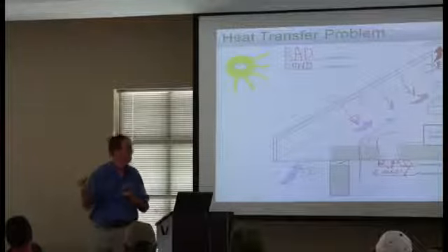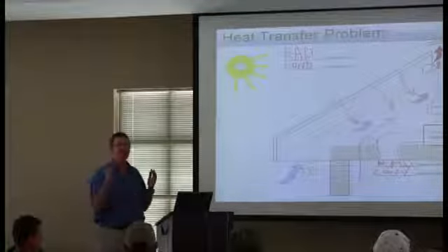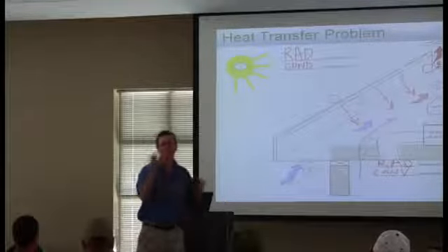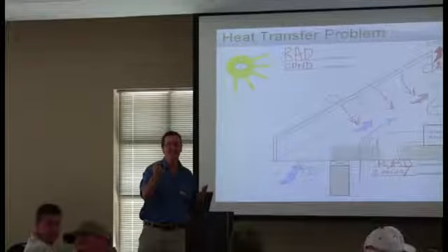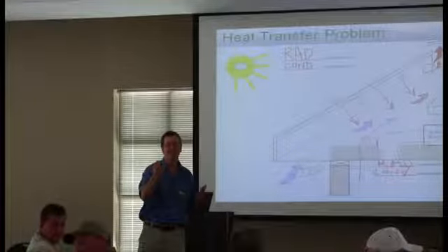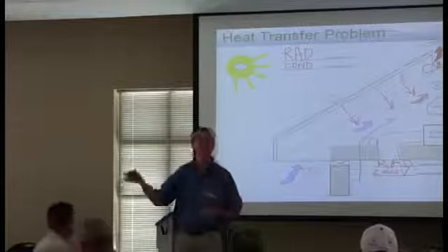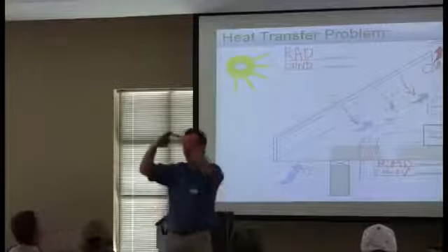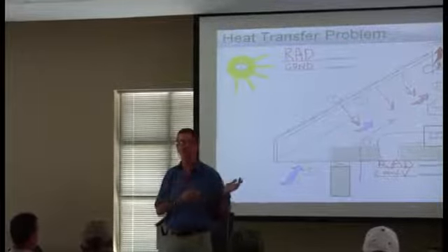Can I throw one more thing? Just a second. We had some people take the course. What's the bonus if the ducts and air handler are inside the insulation? What do we not have to do? You don't have to test the duct system. You do not have to test the ducts. If the ducts and air handler are 100% inside the building thermal envelope, you do not have to test the duct system.